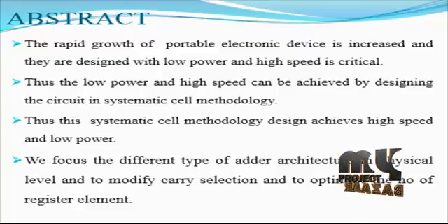Cell design methodology has been presented to design some limited functions, such as 2 input XOR and XNOR and carry and inverse carry, in the hybrid CMOS style. In this brief, we propose efficient 3 input XNOR circuits as the most significant blocks of the digital system, with a new systematic cell design methodology in hybrid CMOS logic style. SCDM, which is an extension of CDM, plays the essential role in designing efficient circuits.